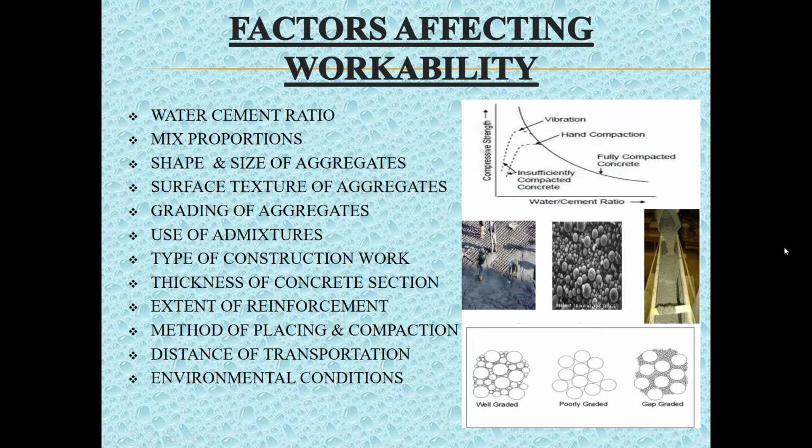From the figure, it is evident that strength of concrete decreases with increase in water cement ratio. The increase in water cement ratio indicates increase in workability of concrete. Thus, strength of concrete is inversely proportional to workability of concrete.